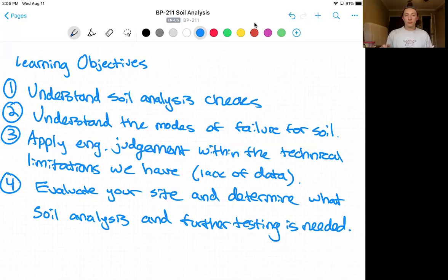So soil shear failure is another check we can perform that becomes relevant when we are sharpening the pencil on calculations and begin to get closer to our true failure by including sidewall friction, bottom slope effects, undisturbed soil weight, and more tips and tricks we've discussed previously and more things we'll discuss before the end of the course.